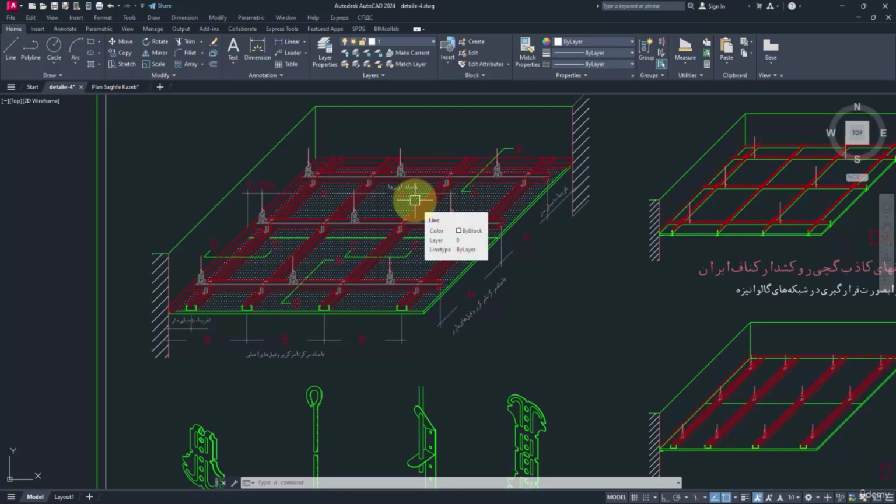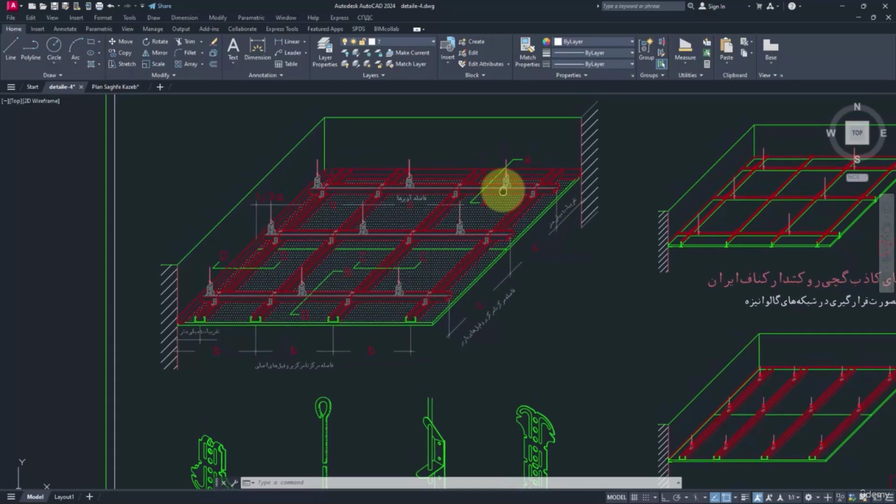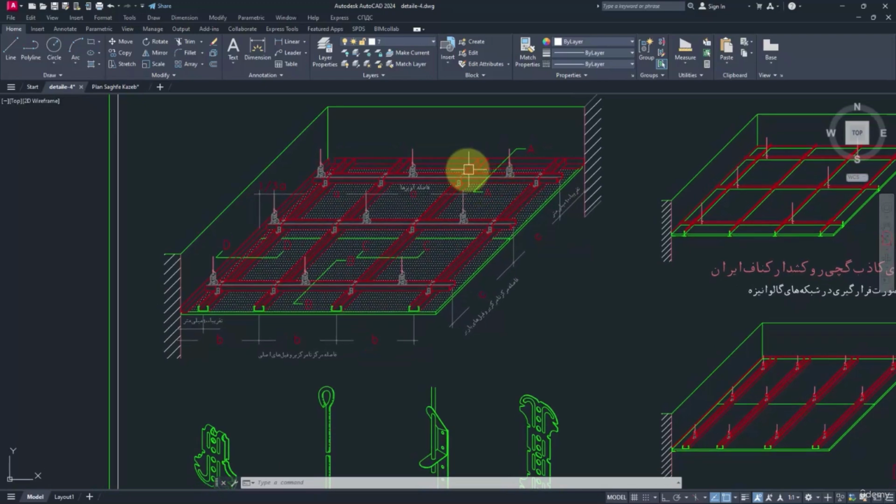So firstly, you have to check the goals and the purposes of the ceilings, and then choose the type and decide on whether to model the details or not. Sometimes we need to provide a schedule table out of everything. But I should say that modeling these details is not helpful for clash detection. However, I have talked more about these in the BIM course.